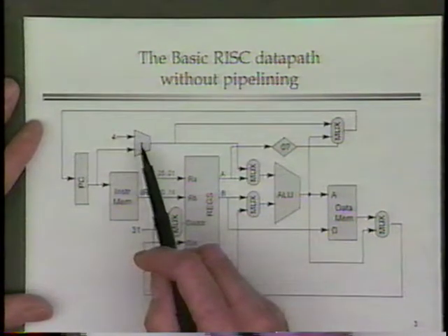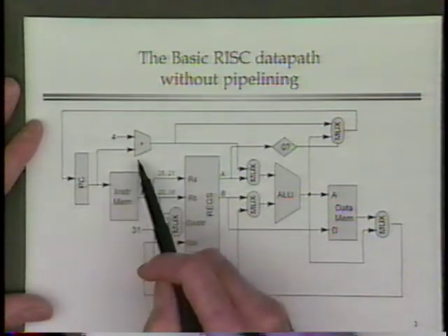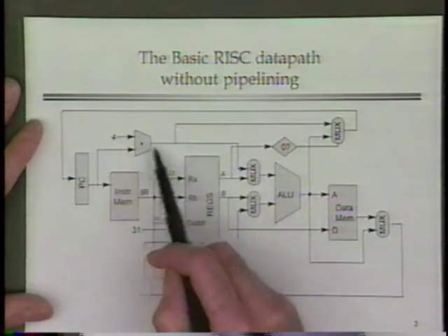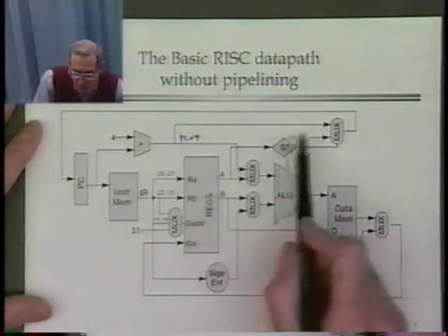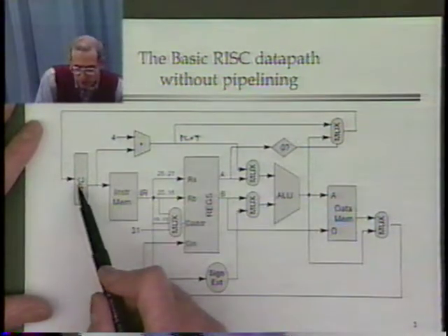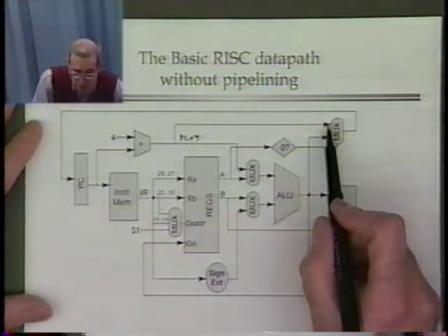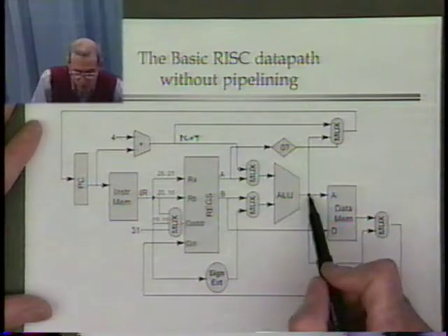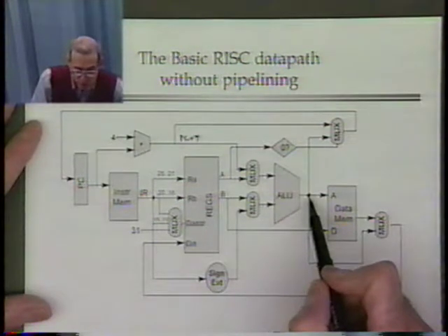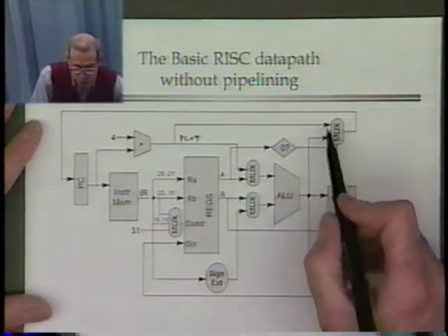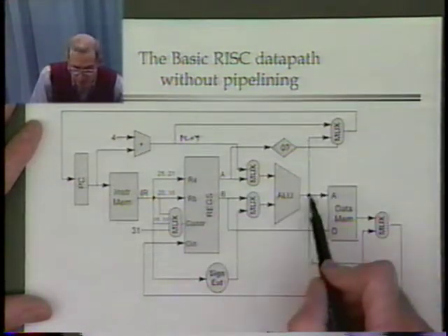In preparation for the next instruction, we need to increment the program counter by 4. This is an adder that does that. Static adder that just adds 4 to the PC, produces PC plus 4. PC plus 4 will eventually have to get stored back into the program counter in order to fetch the next instruction. Sometimes, however, when we do a branch or a jump, we're going to have to choose a different PC, one that we will compute based on the jump and branch addressing modes that we saw, and choose that one instead. So this multiplexer basically chooses whether to store PC plus 4 into the PC or the computed value coming out of the ALU.